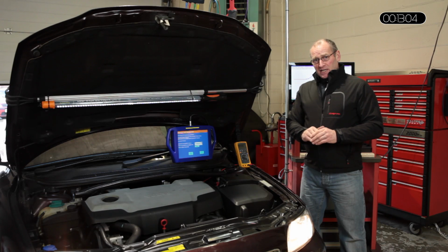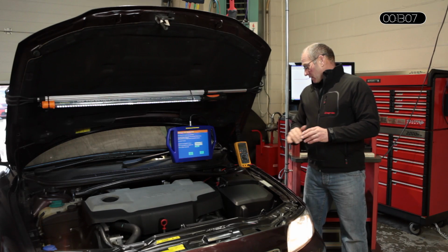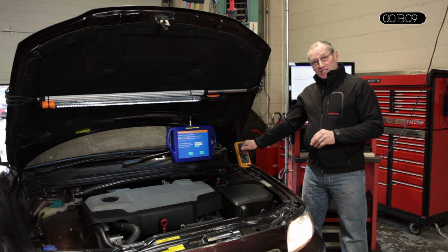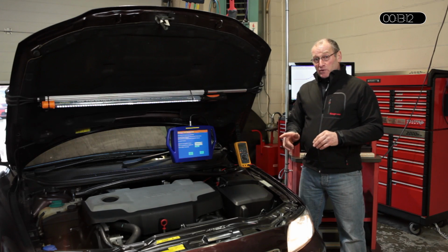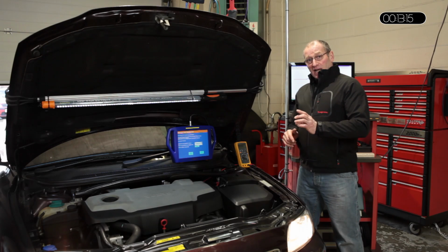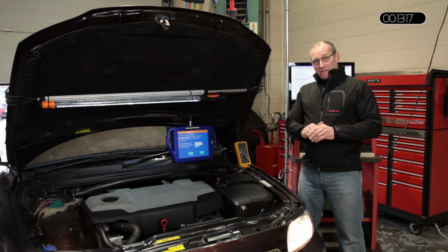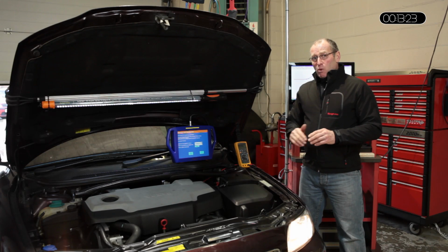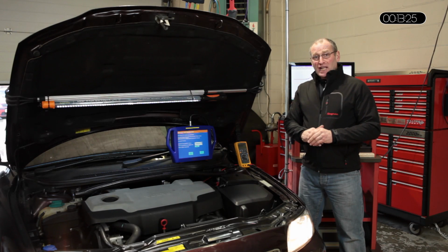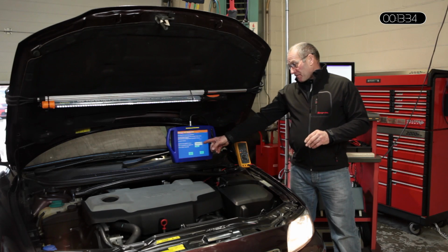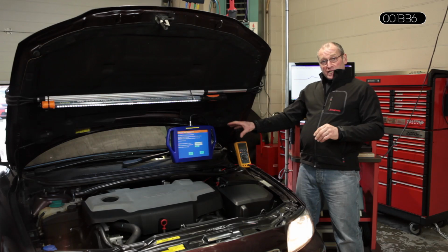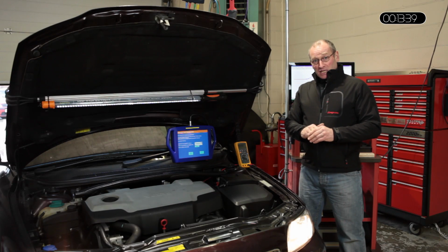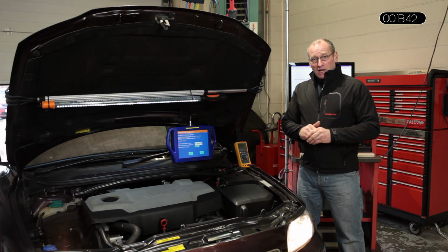Having rectified the problem, we have the same plausibility value, 0.6 at idle, 0.6 static. There is no difference in the pressure static and engine at idle. However, when we drive the vehicle now, the maximum voltage measured with a DMM is about 1.6 volts, which is an excellent figure. That's an acceptable figure, and that's on full load, dynamically measured on the road. And the figures we have from the serial data also have improved dramatically. They're now within the envelope of the correct figure.